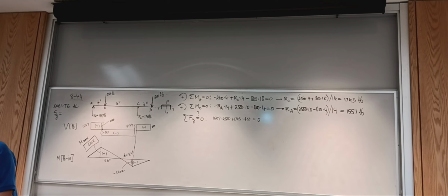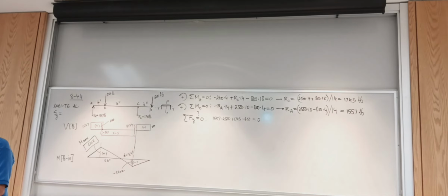So our 6061 T6, page is 787, and yield strength. Okay, it says design factor of 4 in bending. Does not say that for repeated loading. So we go with yield strength and N equals 4.